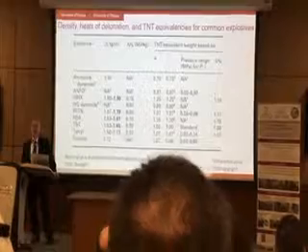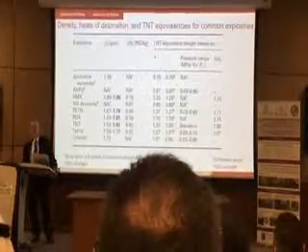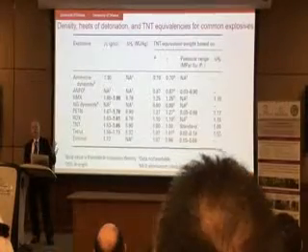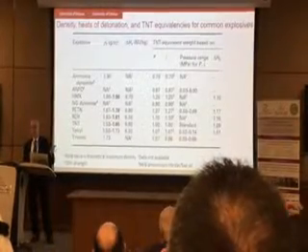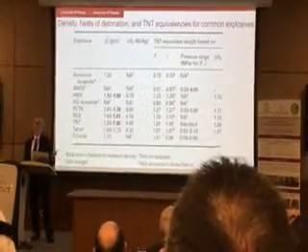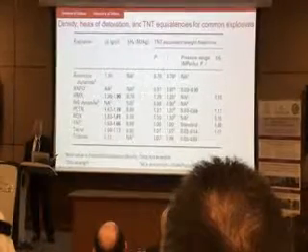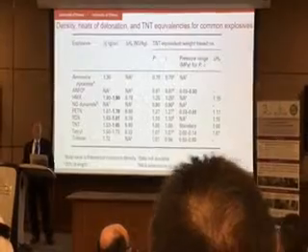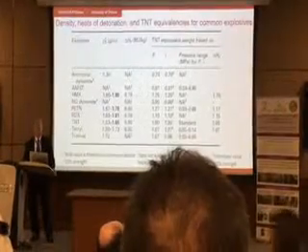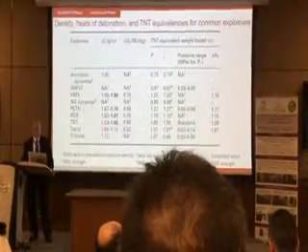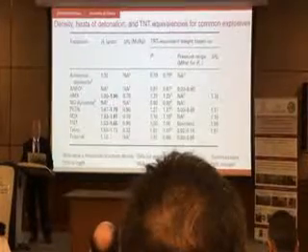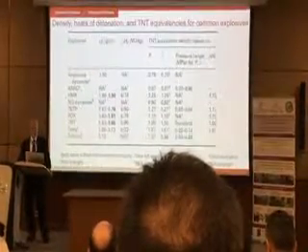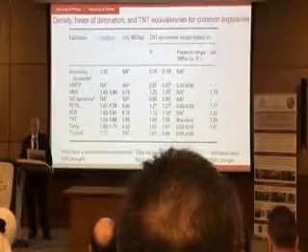And I already mentioned that when we talk about explosives, we talk about the charge weight in terms of TNT equivalents. Here you see different explosives and TNT is right here, and the conversion factor is 1, and then if you have RDX, you have to increase it by 1.1.